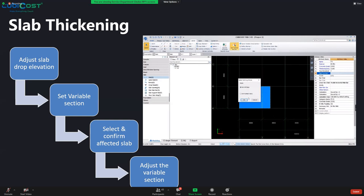Set all sides or set multiple sides. What is the difference between these two? Basically, set all sides will detect the sides that already have two slabs combined and require forming the shape. Whereas set multiple sides is where you can select specific locations to do the variable section.